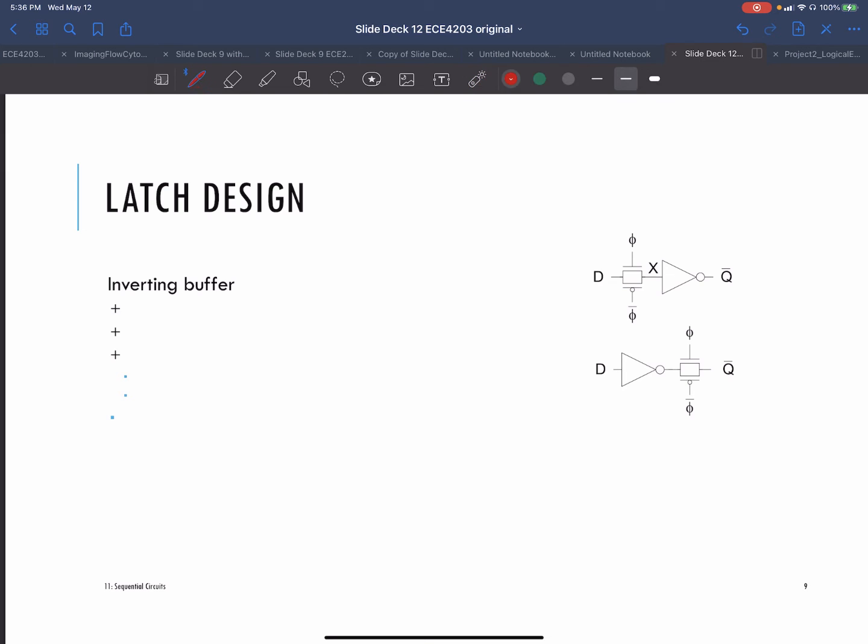So here you have a situation, let's say if you have an inverter at the output, you have the added benefit that this is restoring, meaning that if you're sitting here at a sort of 1, you'll get a real 0 here. The next inverter will clean up the logic level to some extent. So it's a restoring level, and if something's trying to drive this, the inverter will stop it, so there's no back driving.